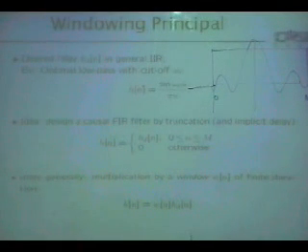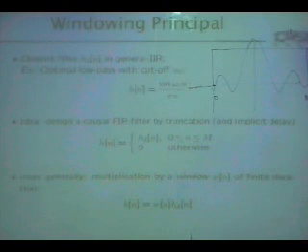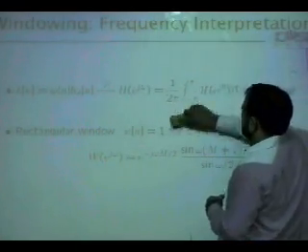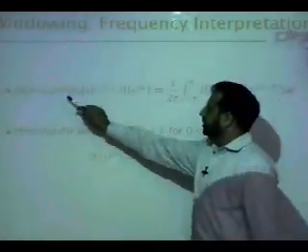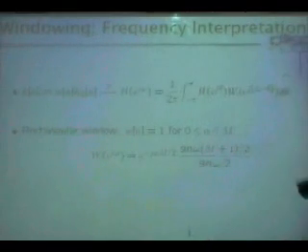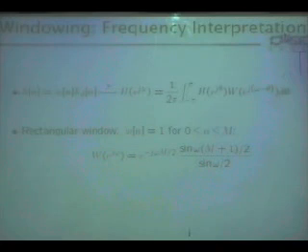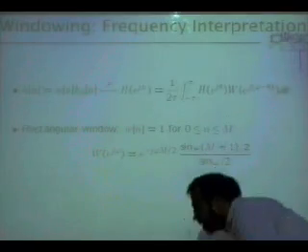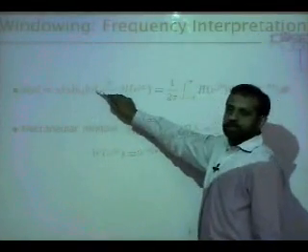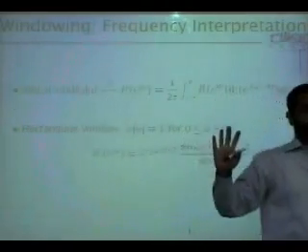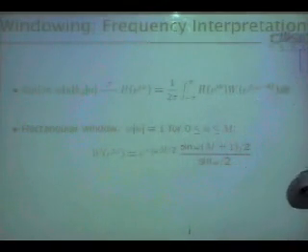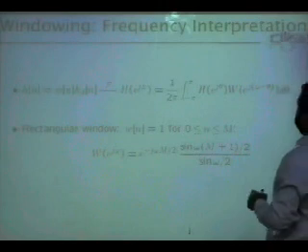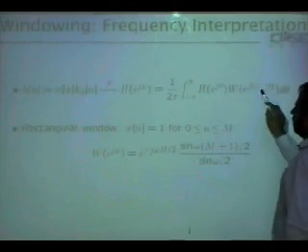Right? And this is to learn what happens if you window a sinc function. Okay, so multiplication in time is convolution in frequency domain. And it is a periodic convolution. Why? Because you take the Fourier transform of the window and the Fourier transform of this, and then you have to make multiple copies at every 2 pi. So once you are flipping and dragging, you need to take the copy along, and I'll show you a slide which depicts this. So this is the formula for convolution.